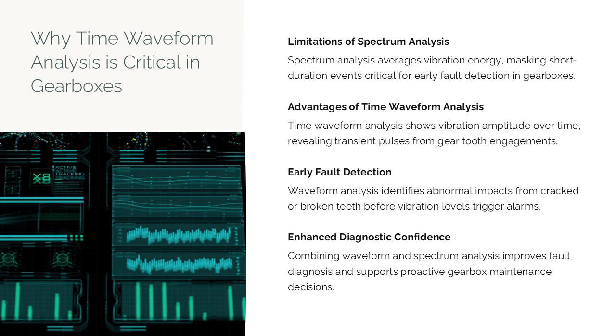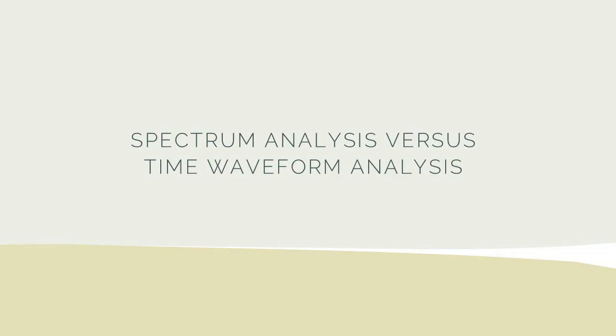Time waveform analysis also enables intuitive interpretation, as it closely represents the physical reality of mechanical impacts and load variations. When used alongside spectrum analysis, waveform analysis significantly enhances diagnostic confidence, supports proactive maintenance decisions, and reduces the risk of unexpected gearbox failures. Limitations of spectrum-only diagnostics: spectrum analysis versus time waveform analysis.